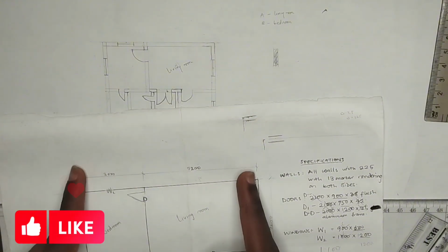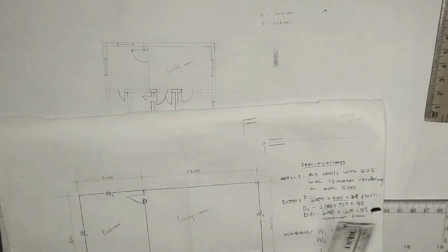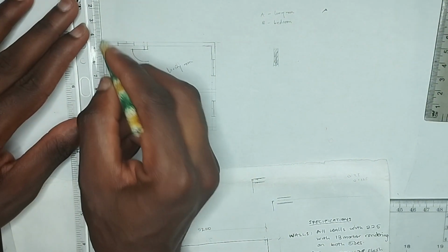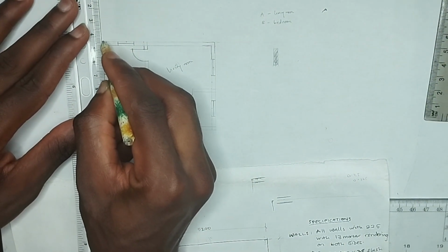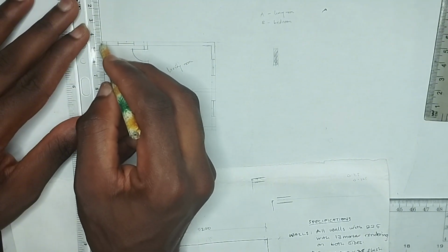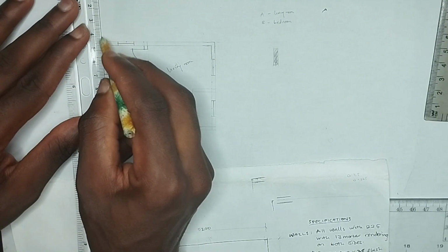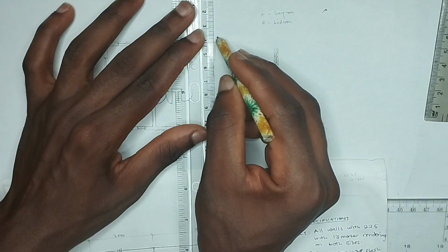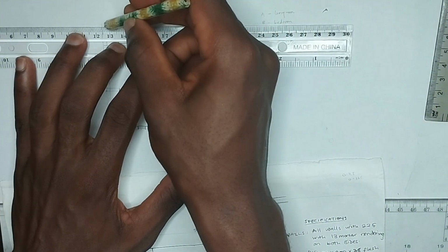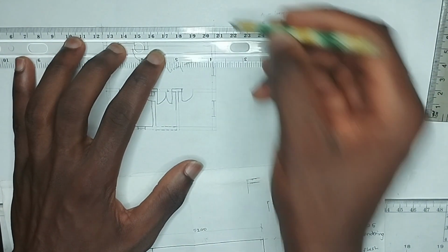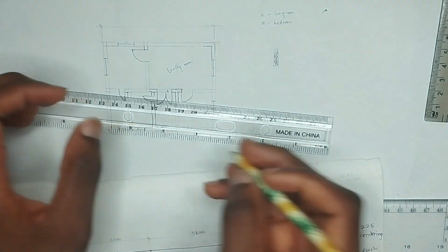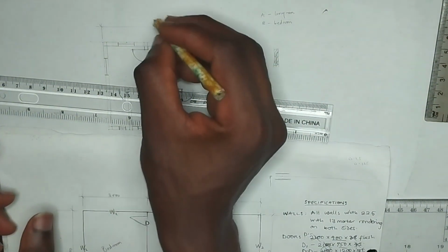Okay, so dimension our block. We are just going to project outward. Okay, we'll project from, let me dimension this particular part to serve as an example. We'll project from this point. We won't allow it to touch our block, and you can also allow it to touch it depending, but it's better and neater if it is not touching the main plan. Okay, so we'll project also outward like this, then project outward like this, and we make it to pass through this a little bit. Okay, then we strike it like this. What's the total length? Which is 8200.